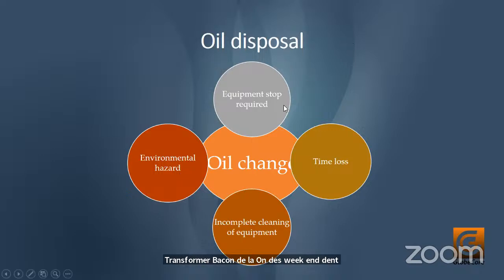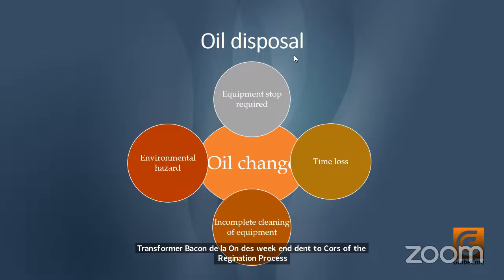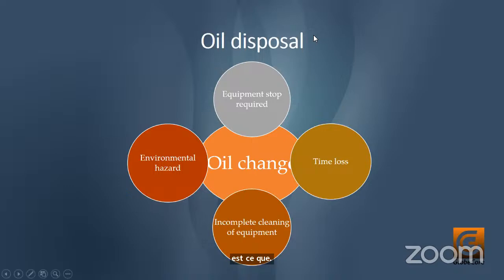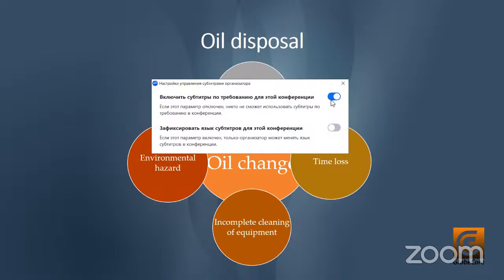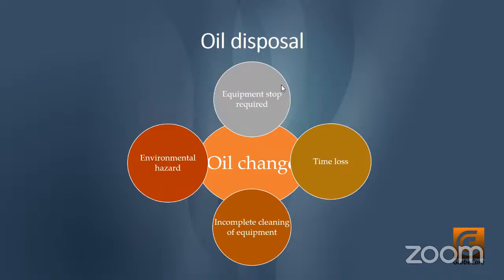A significant amount of contaminants remain inside the transformer, which act as catalysts, accelerating the degradation of the new oil we just put into the transformer. In somewhat less than 1 year, the new oil will have properties close to those of the oil that required regeneration. So we can say that due to cross-contamination, the new oil has very bad properties after approximately 1 year of operation.